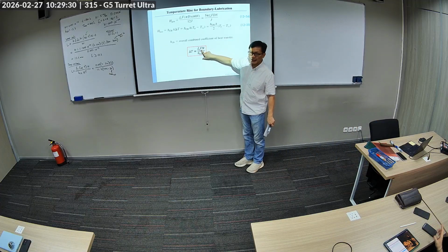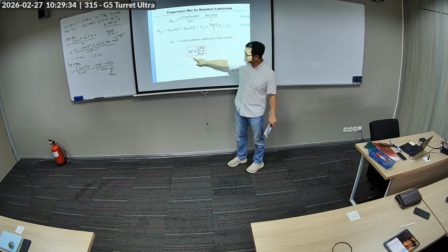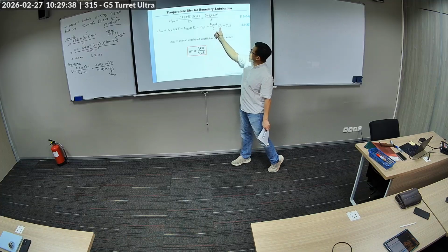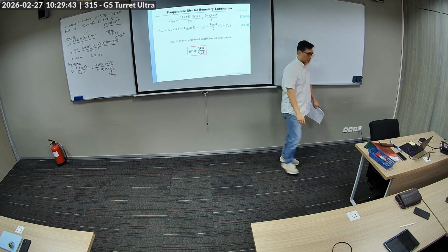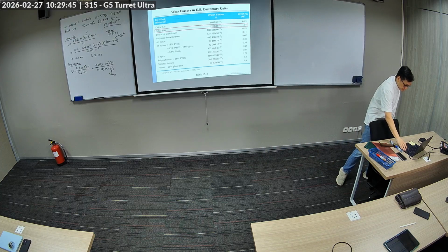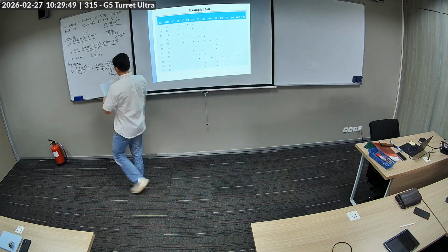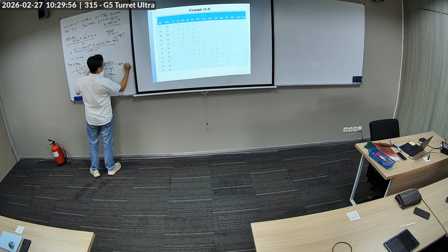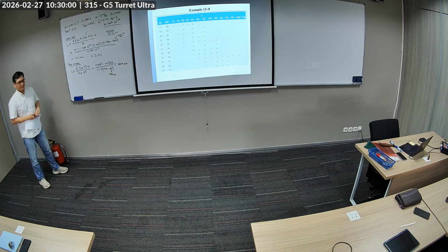Now the F, I'm multiplying with ND, and I rearrange for L. And delta T is the temperature of the bushing minus the ambient temperature. So we end up with a number, 38.4 millimeters.